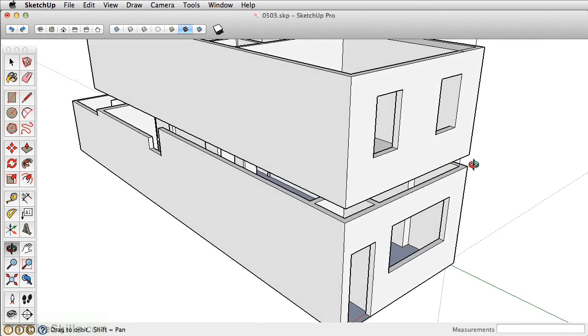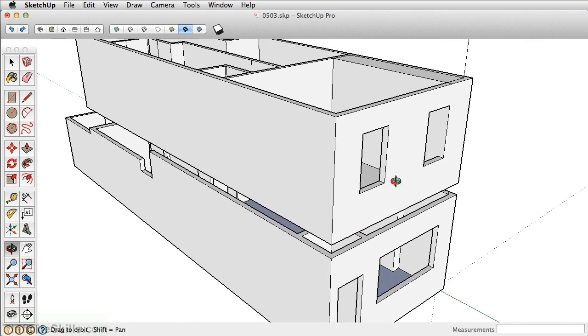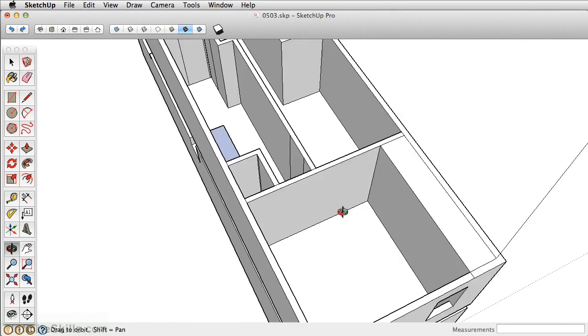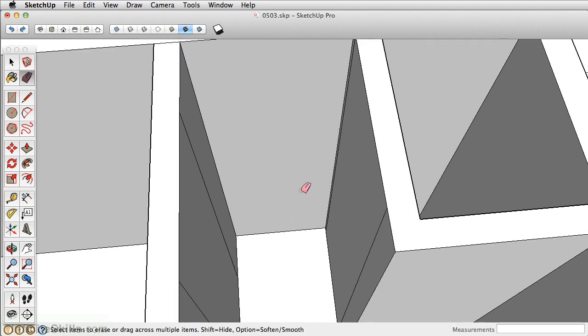We got our second floor. We'll deal with the gap here in a little bit. We need this doorway here. Let's draw this door another way. What we've done here is we've created the opening, and I forget how wide this was. So let's take the measurement. We can see it's 34 inches. So we would need to draw a line 2 inches and then 2 inches and then draw our rectangle.